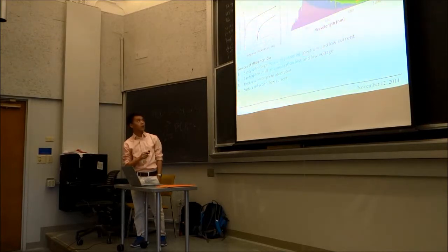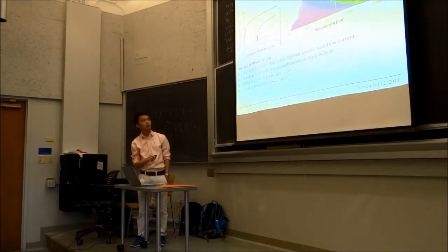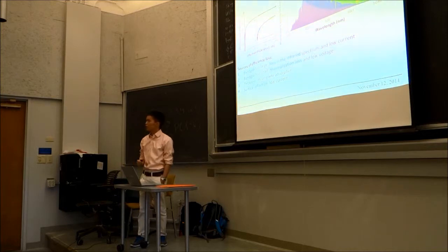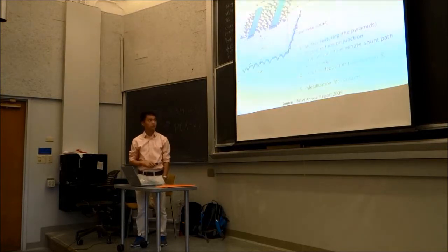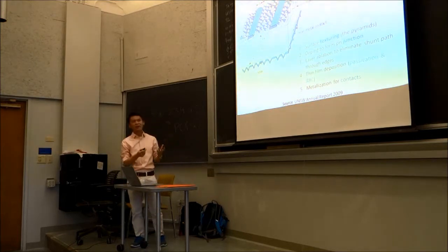This graph shows you the simulation, for different thicknesses, of the photocurrent you can generate. It basically tells you that when you increase the thickness, you get a larger and larger photocurrent, but at a certain point it doesn't quite make a difference. It flattens out eventually. The black dot here is 300 micrometers, the commercial photovoltaic solar cell thickness. So those are the physics, and now let's look at how people actually make them commercially.